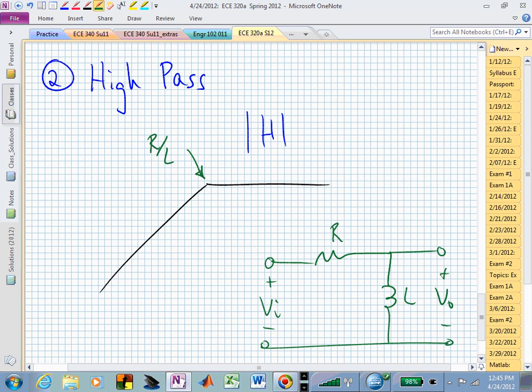And that's one reason why we are going to concentrate most of our effort on low-pass filter design, because you can create high-pass from low-pass by simply replacing the S's with 1 over S's in your transfer function. And now you've mapped this low-pass behavior into a high-pass behavior. Does that help with your comment? So the comment was valid.